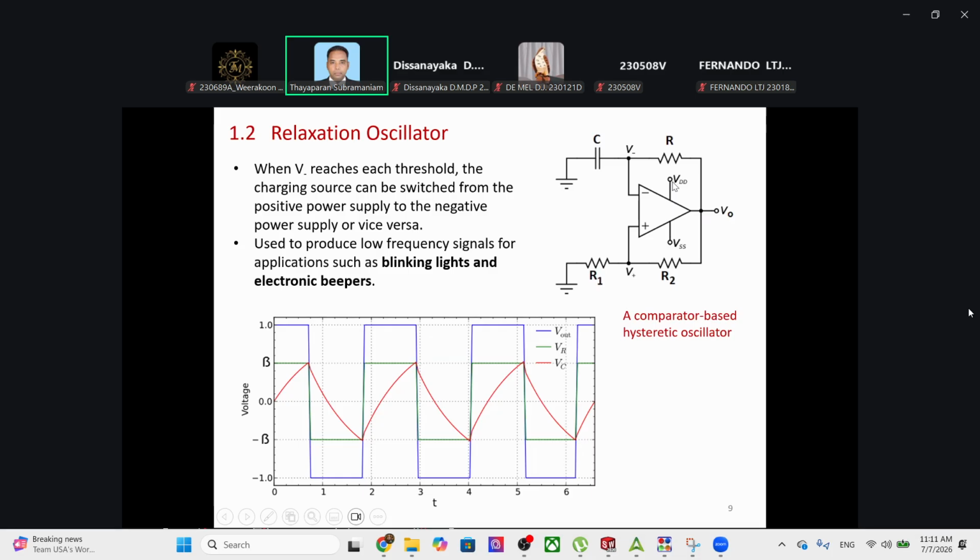If you have a transistor between this VDD and the positive terminal of this op-amp, the transistor is a PMOSFET. You have to have a PMOSFET here, not an NMOSFET, because NMOSFET means a problem. PMOSFET, because it's close to VDD; NMOSFET we connect to the side close to ground. Okay, so then we can have power gating.